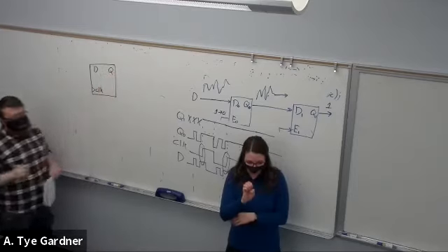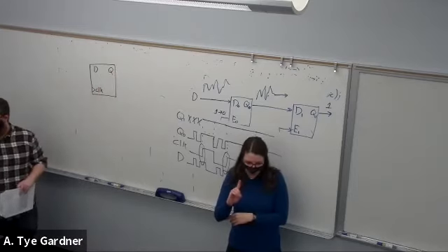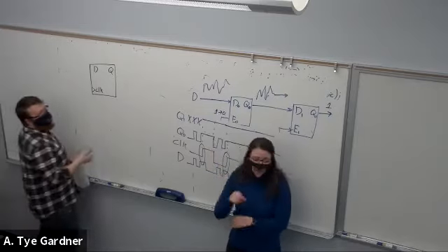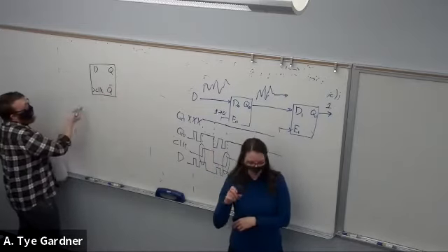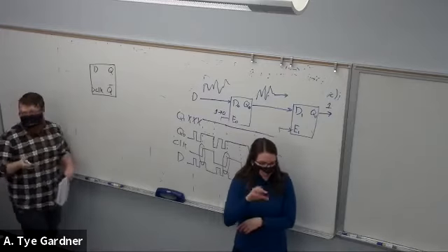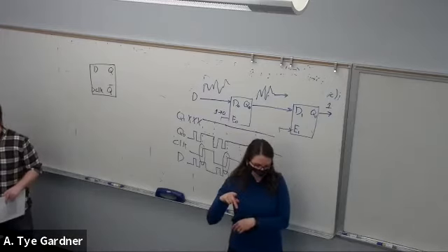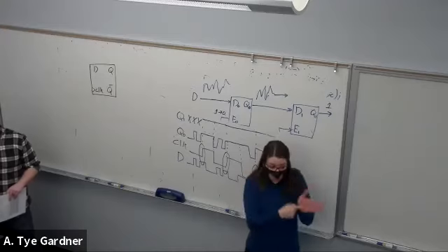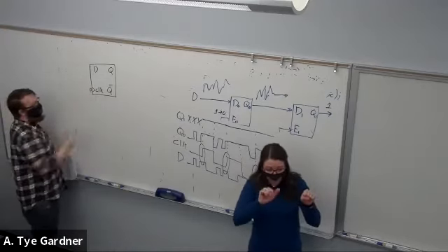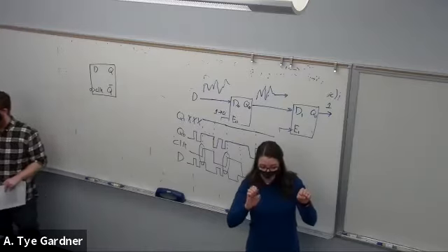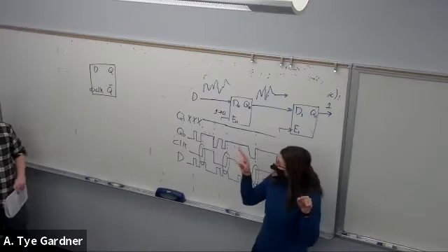This is what we would call the D flip-flop or the DQ flip-flop. Just like most, the output will have a Q and Q bar. If you wanted to indicate that this was an active low or falling edge D flip-flop, you would just add a little inversion bubble at the clock. Not surprising, right?